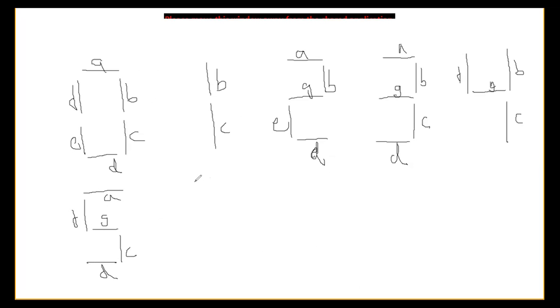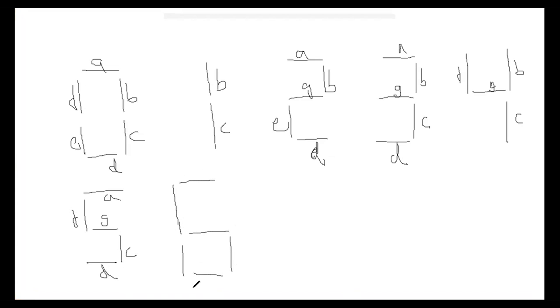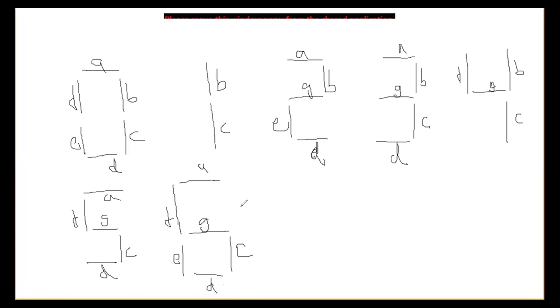Next you can go for the 6 like this. Directly I am taking here the 6. I would get the 6. So suppose if I am writing this as 6 like this, it is also 6. But otherwise you can take it like this also, the 6. Okay. So A is on, B is off, C, D, E, F, and the G are on. Okay, only to get the 6, B is off.